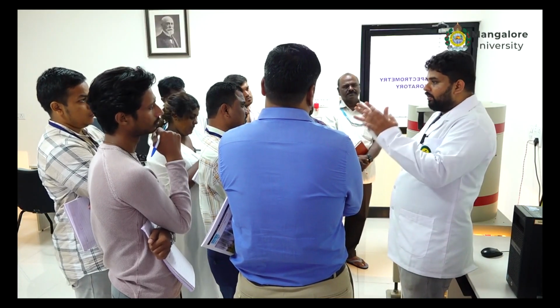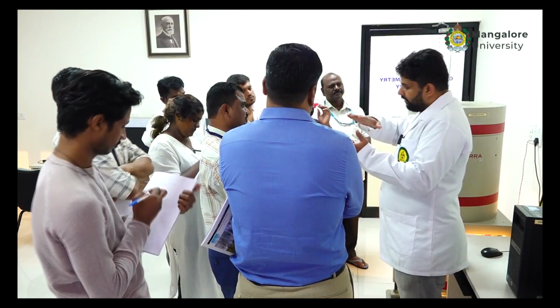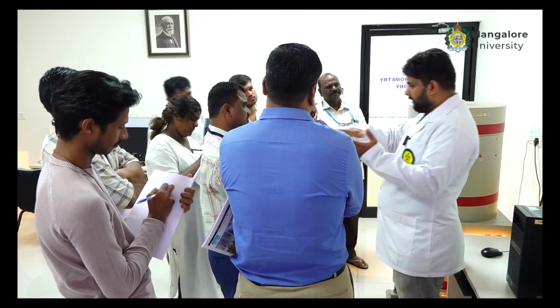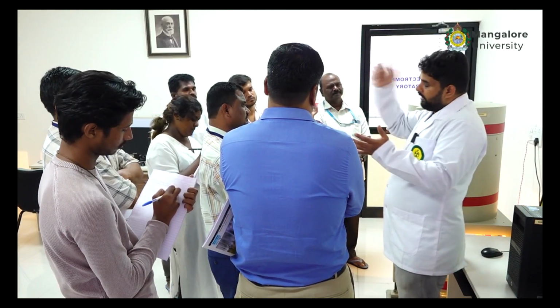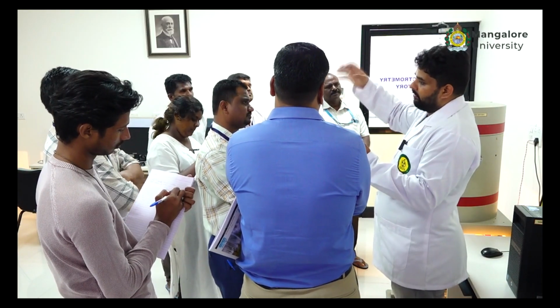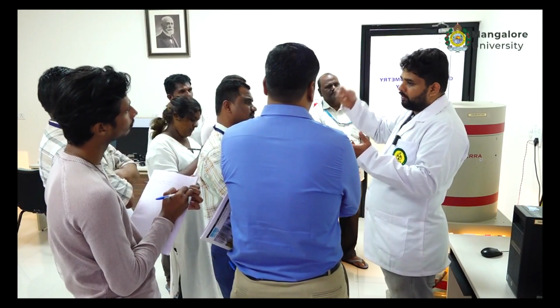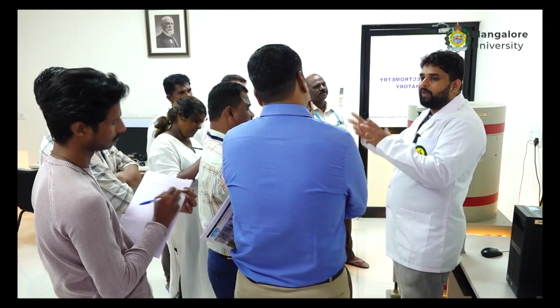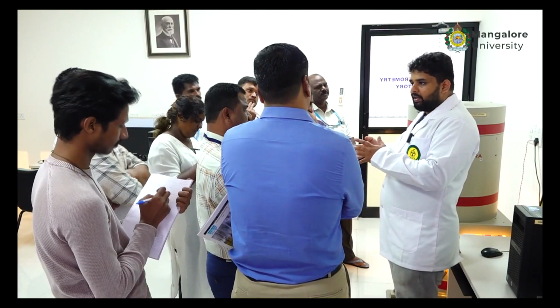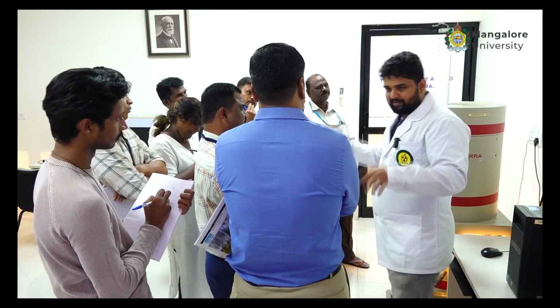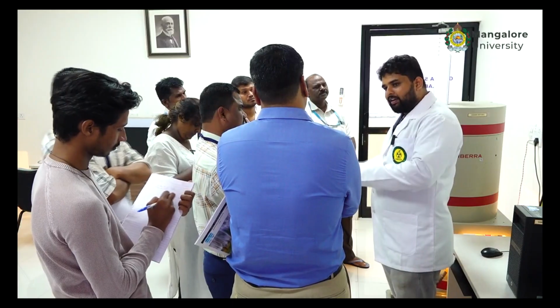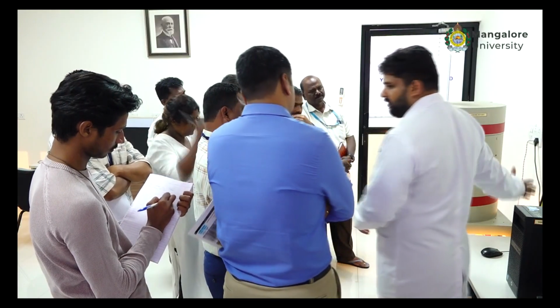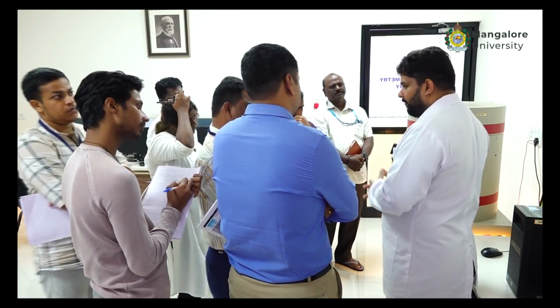When you reverse bias it, a large area of depletion region is created. When your sample has some radiation sources, radionuclides, and it falls on this depletion region, an electron-hole pair is generated. That means a current is generated. That current is what we get here as peaks. I will tell how it happens.